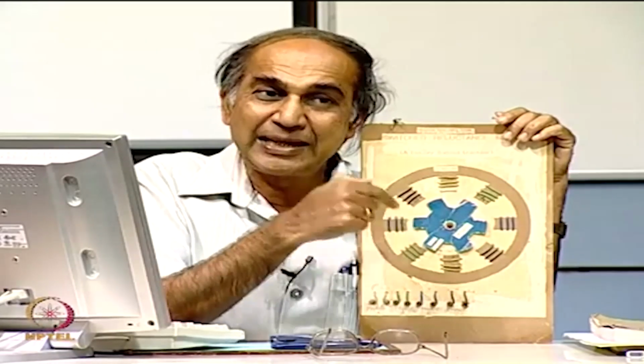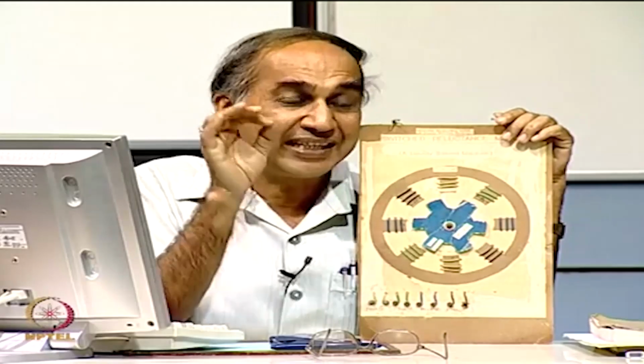Now, this inductance gradient you have to know. So you must pass a current at the right time with respect to the rotor position. You can't pass current as you like, this is another problem. The switching instant depends upon rotor position. Therefore, you must have electronics to detect the rotor position. Another important thing for this machine is that rotor position sensing is important. You must sense the rotor position and then pass a current through that.